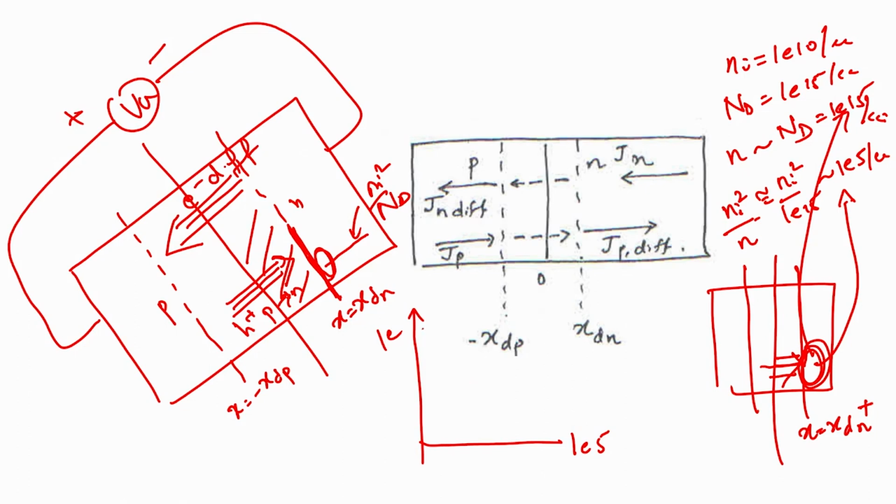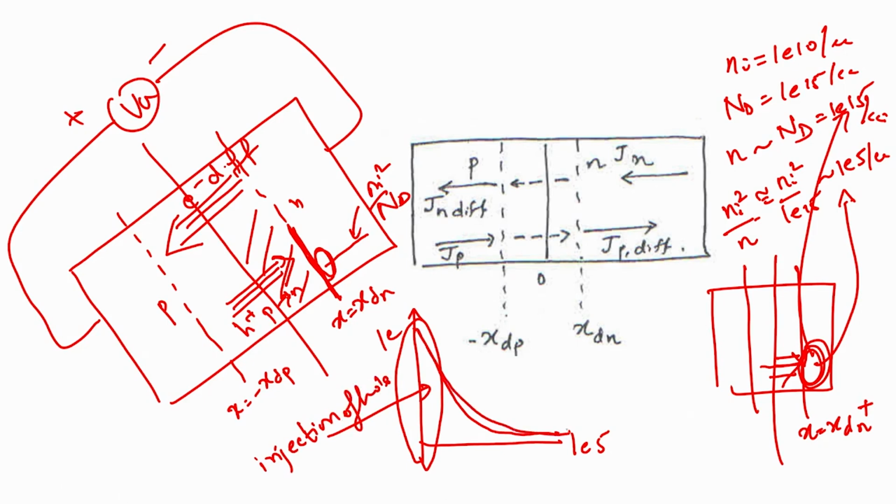And because of recombination, this hole population is going to immediately start declining in the semiconductor. So, it is as though you see a huge injection of minority carriers. The holes are the minority carriers in the N type material. So, there is an injection of minority carriers, and this minority carrier population is going to decrease with distance because of recombination, and we have already looked at this phenomenon when we looked at the continuity equation and recombination generation mechanisms.